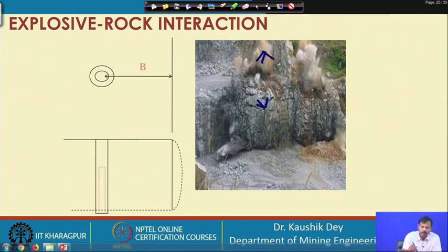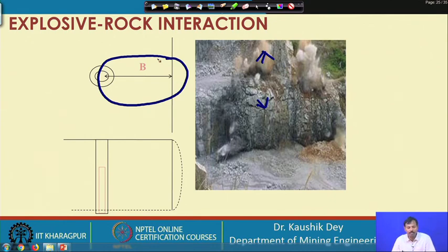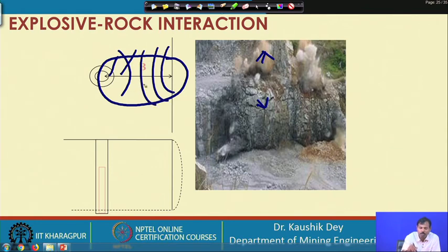Our objective is to choose a burden such that the crushing zone, radial cracking zone and tensile slabbing zone are completed ahead of the gas reaching this position.